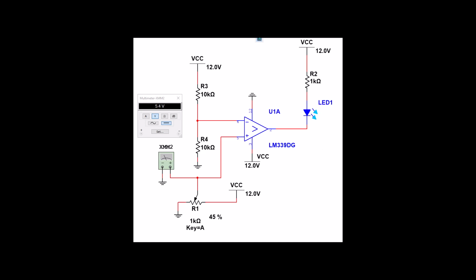Okay, so let's go above 6, and it should open up and allow the LED to turn off. And it did. 6.6 is greater than 6, so we go to the positive rail, which closes this off and doesn't provide a ground path, and it's off.